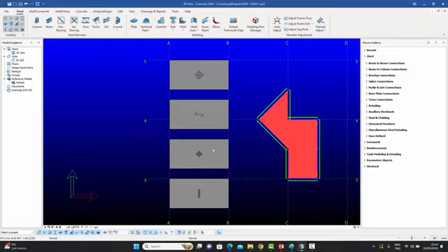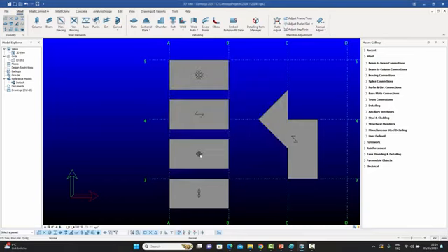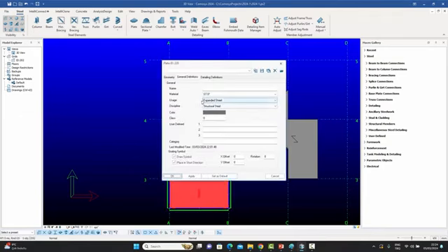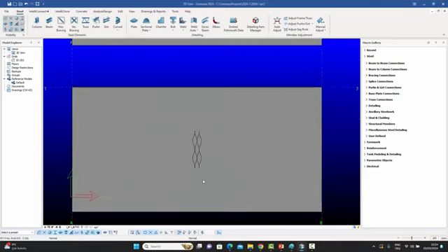Similarly, we have these two new options we did not have at all. This is the diamond plate in the usage. It's all being done from the usage, by the way. The diamond plate option has been added. This wasn't there previously. And when we choose that, then we get this symbol by default. And similarly, this fourth one has been added, which is for expanded metals, expanded sheet. This one gives us this particular symbol.